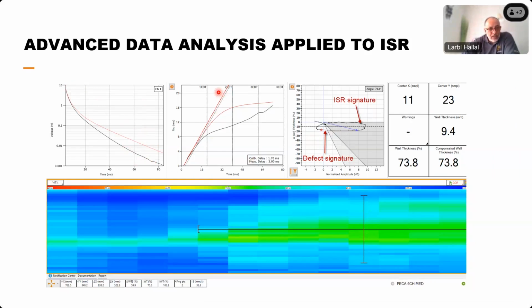If we look here at the Tau-Scan, same. We have the infinite wall and the bending region giving us some, let's say, acceptable signals. Just the plateau wall is showing something caused by mass effect, and this is the interference coming from the insulation support ring.